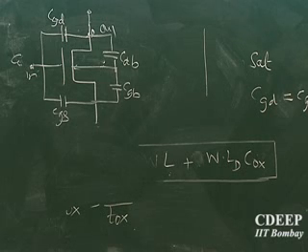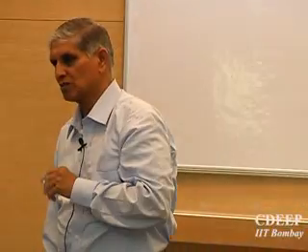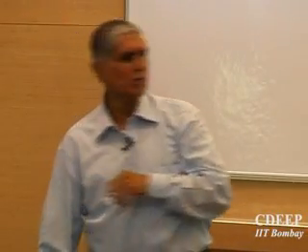At what frequencies? Much higher frequencies. So the limitation of an amplifier actually comes from this feedback capacitance, which is CGD. Is that correct? Which is very small in general, but at higher frequency, this may have the influence of returning some output signal to the input signal. Is that correct? This is very, very important in all analysis of analog blocks ahead, because this CGD limits you. Is that correct? CGD limits you.